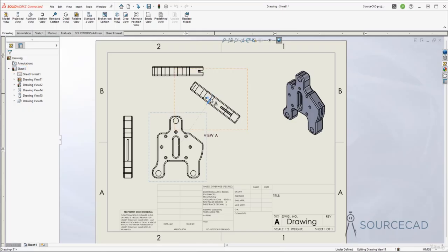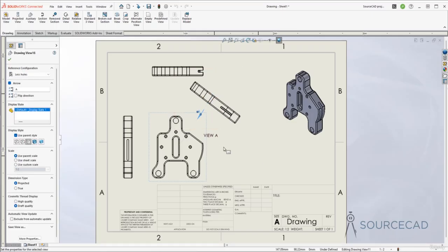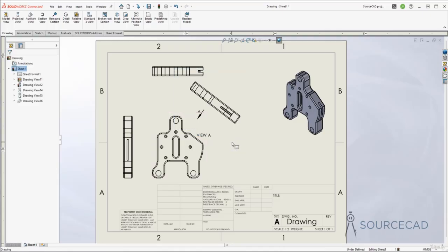Maybe let's just move this arrow out of this view like this, and I'll just move this label close to this edge. And that's our auxiliary view. Now in this case, this edge right here is actually this edge, this distance to this. So you can actually add a distance right here or from this point to this, and that's going to be exactly the same.